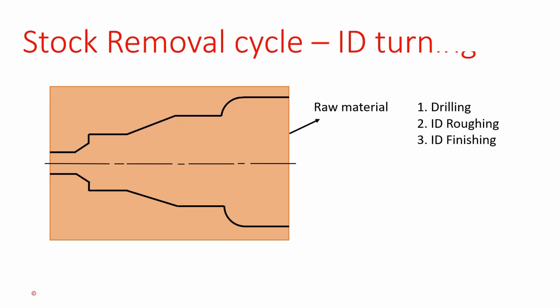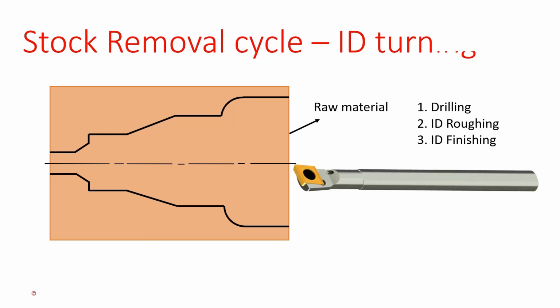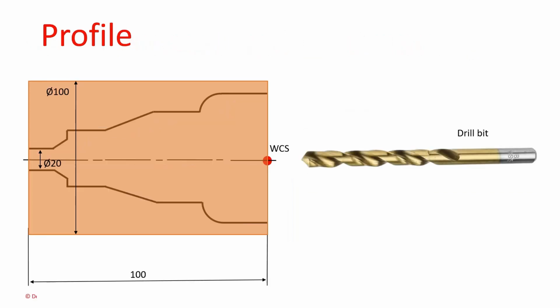Why is drilling required before doing the ID profile? For the selected ID profile, the selected tool will look like this. This can't be performed without any hole. So for creating a hole, we need to choose the drilling operation. Let's start the discussion on the drilling operation for the selected drawing.